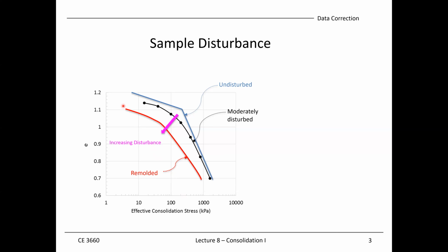And if we have an extreme case, for example, we take our soil samples back to the lab, we totally mold it, dry it out, and put it into powder, and then we reconstruct it with the clay powder, mix it with water again, and then apply all the stresses.